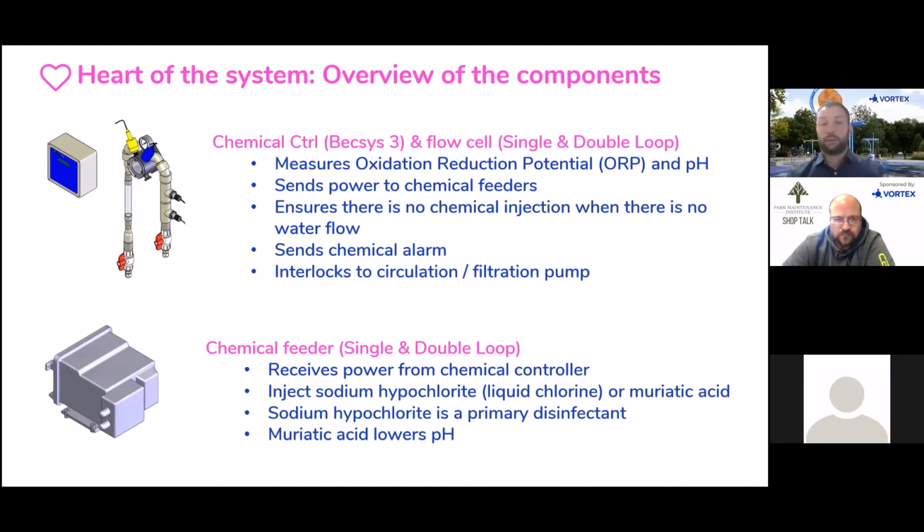It will send a chemical alarm, again, super important, to the Splashpad CPU, telling the Splashpad to turn off if it does go into chemical alarm. So you have peace of mind knowing that if things do get out of whack from a chlorine or acid standpoint, your Splashpad will shut down before spraying water on any users that happen to be there.